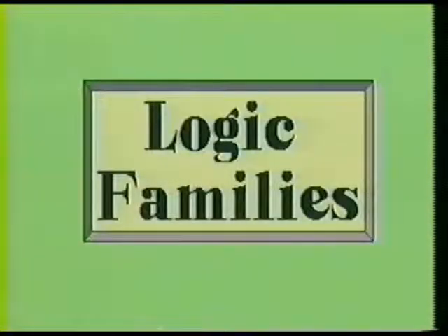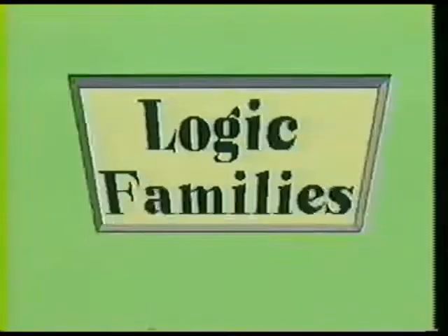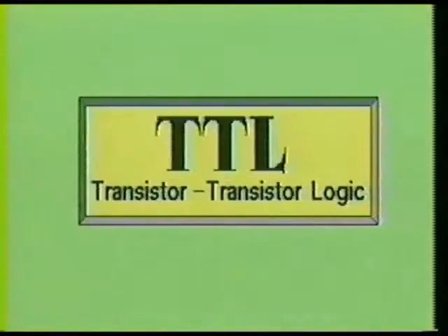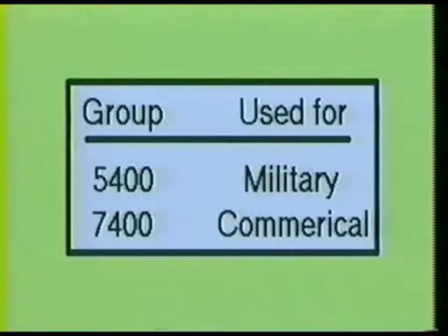We will now cover some of the more common logic families found in today's electronic equipment. The first family we shall cover is the TTL. TTL stands for transistor-transistor logic. The TTL logic is the most widely used of the logic families. There are 2 basic groups of TTL logic circuits. These are the 5400 group, which is used for military equipment, and the 7400 group, which is used for commercial equipment. The military group requires more rigid specifications than does the commercial group.